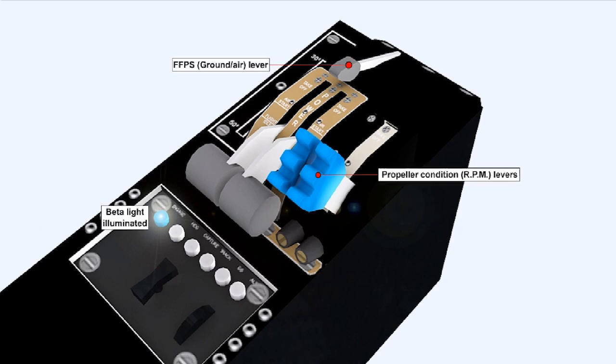While the aircraft is taxiing, there is insufficient RPM available to bring the propeller control unit on speed, and it's therefore unable to take control. Propeller RPM is controlled by movement of the engine power lever within its range below flight idle.